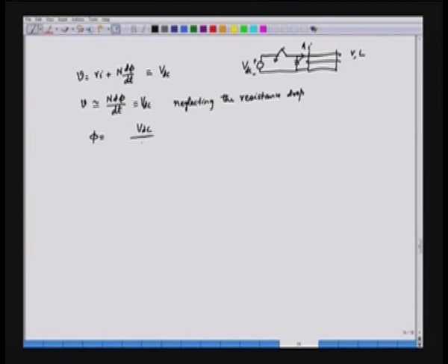the integral of VDC by N into dt, and that is equal to the integral of VDC by N into omega, where omega is the rotor speed. We can multiply omega in the denominator and also in the numerator. So, we have d omega t, and that is equal to the integral of VDC by N omega into d theta.